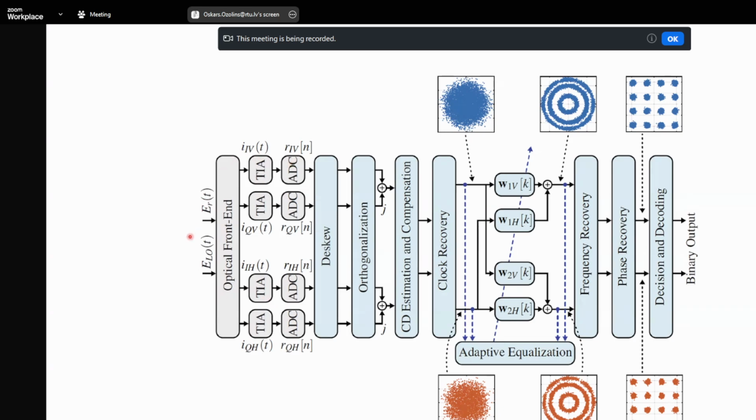What happens here is that we don't really control the state of polarization in a fiber. In practical lab experiments, one may use a polarization controller. If you only work on one polarization, you could optimize and maximize only that polarization. If you tune the polarization state, then the electrical signal for these two photodetectors is going to be maximized. What we do next is after this ADC.